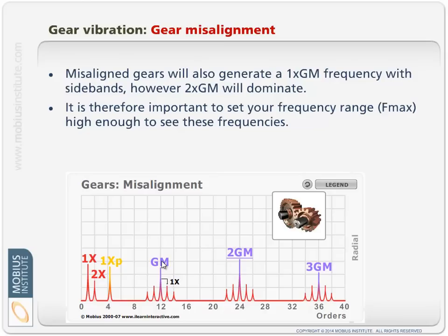I guess with all vibration analysis, one of the things that I think is the most important ability of a good vibration analyst is to be able to transform yourself down and think about what's happening inside the machine. You can do it in one of two ways. You can think about the various faults and think how that's going to change the vibration. What forces will change? What modulation will occur? Is there impacting, how is the vibration changing? And that way you can imagine why the spectrum changes the way it does.